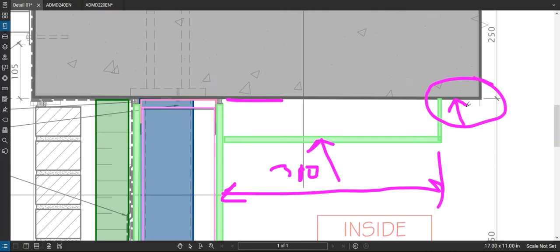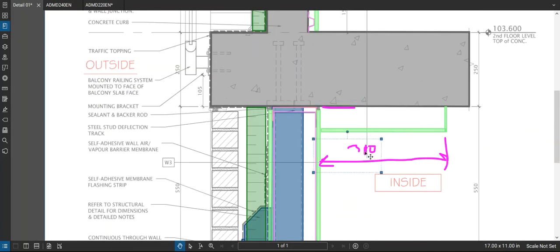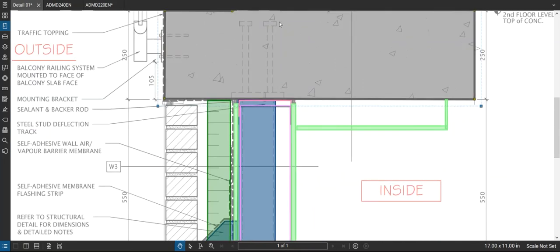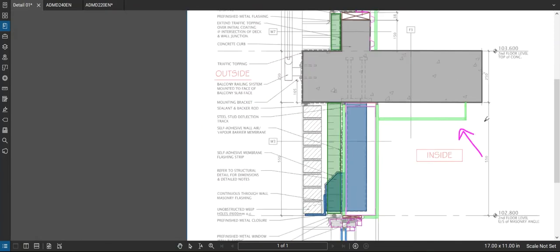I can't write very well on here, but by the time you got to the concrete here, it'd be warm enough that you wouldn't have condensation occurring. But that's garbage in my opinion. That's a pretty terrible solution to the problem. But I have seen that done. And also on the inside, you have to think about what you're looking at here. It looks like maybe you have painted exposed concrete there, and then all of a sudden you've got this little build out there.